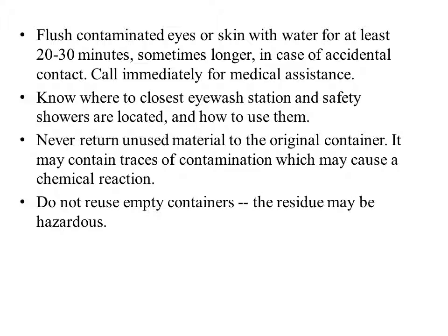And we should also know where the closest eye wash station is, and where the safety showers are located and how to use them. That means if we accidentally come in physical contact with the chemicals, we should not be running here and there looking for the eye wash station or safety showers. We should know which is the nearest eye wash station or safety shower, and of course we should know how to use them.